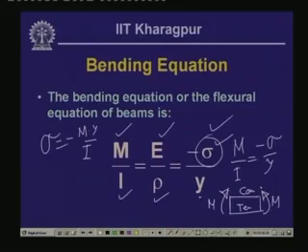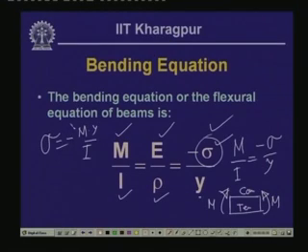Because of the bending acting in this segment, the bottom fibers undergo stretching, which is tensile, and the top fibers undergo compression, which is compressive. Now, if we apply the positive bending moment in this equation, we get the stress as negative, and the negative stress indicates that it is compression.